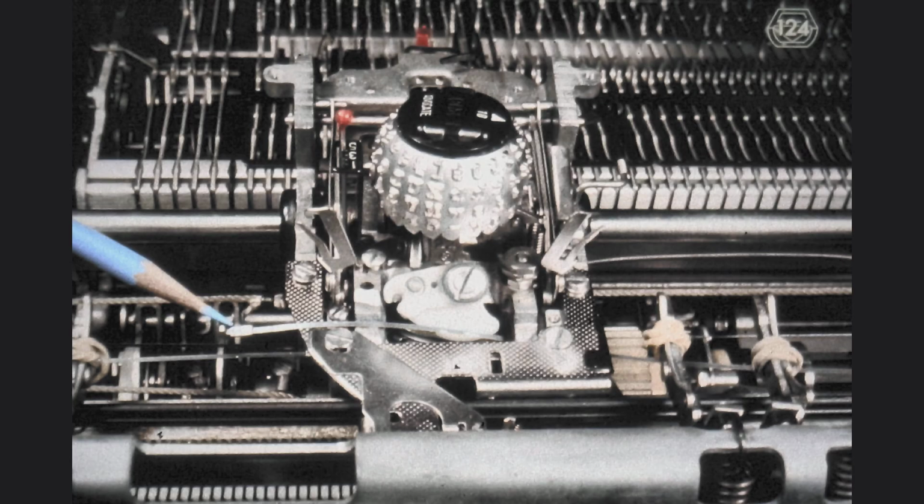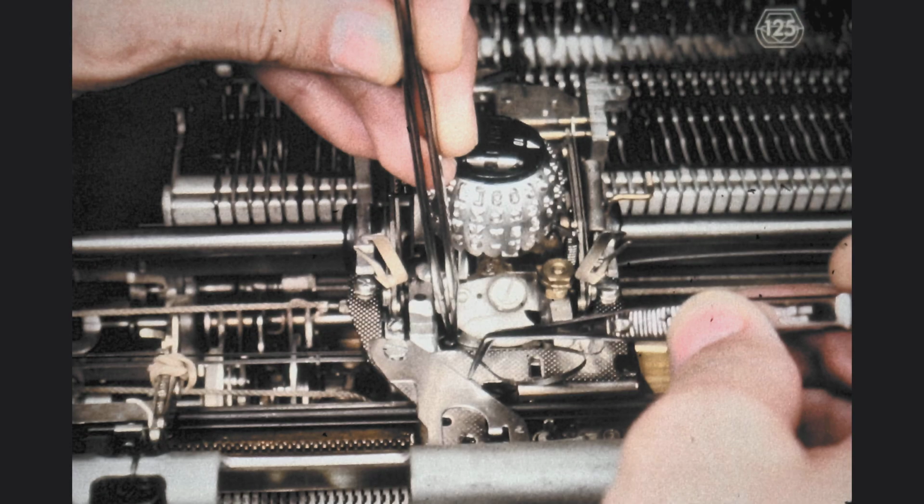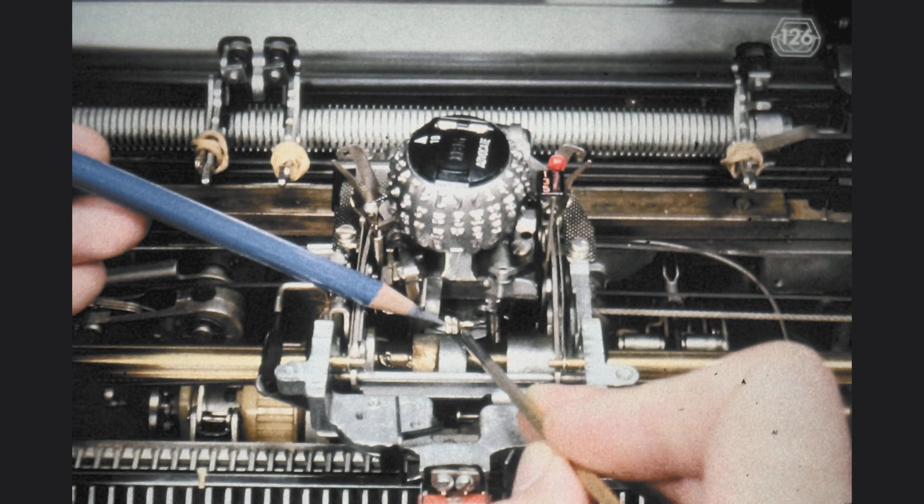shown here. Using 2 pairs of tweezers is by far the most practical method of feeding the tape through the rocker, over the rotate pulley, until it comes out at the front of the rocker. But if you do not have 2 tweezers, or do not like to use them, you can even do this with your bare hands, with the sole reservation that you should be very careful not to cause any sharp bends in the tape. Be sure to recheck the direction of the tape twist before you feed the tape through the rocker. This is a time when the IBM spring hook is an almost indispensable tool.